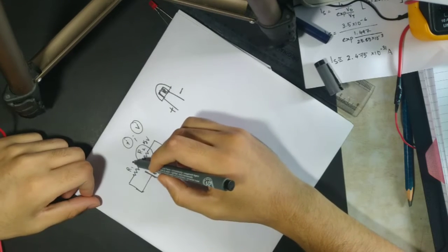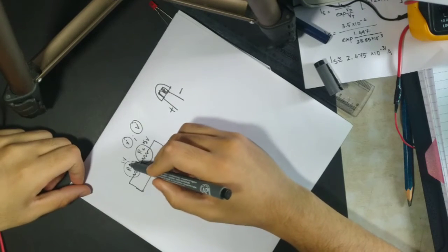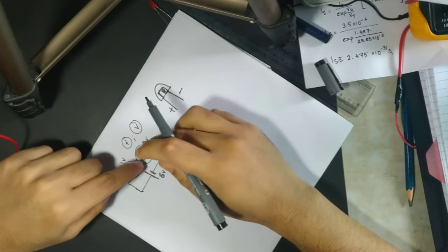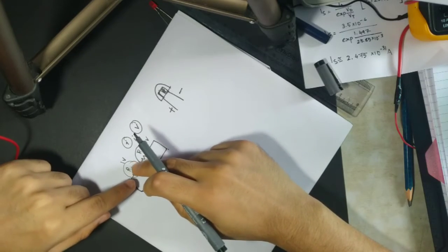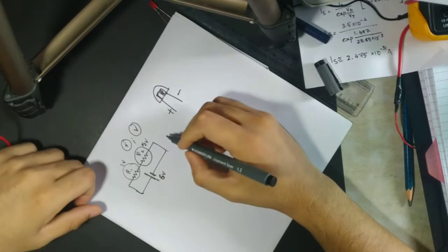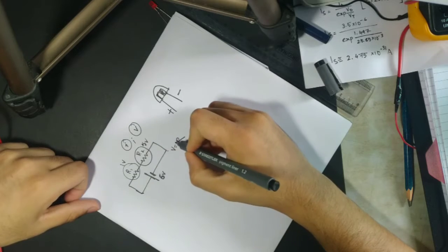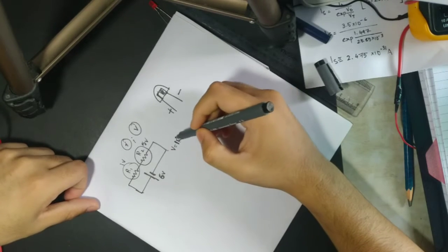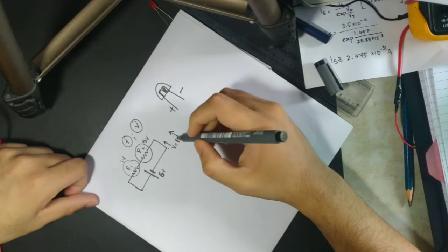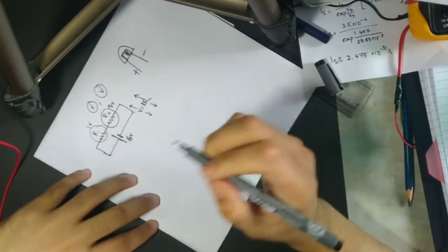So what will be left for this resistance? Only 1 volt. Or you can say that this resistance is taking 1 volt and this resistance will be taking 5 volts. So the voltage drop across this resistance will be 5 volts and across this resistance will be 1 volt. This is determined actually by the equation V is equal to IR. Since the current through both of these is the same, constant, definitely we can see that the resistance which is higher will have a greater voltage drop and which is lower will have the lower voltage drop. So this is the concept of voltage drop.